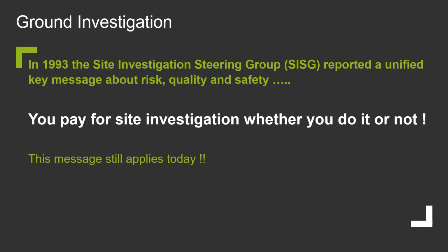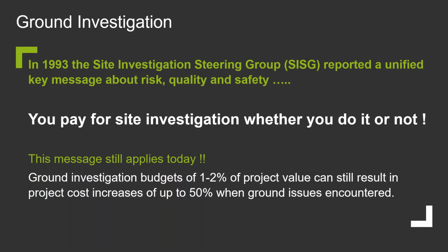So a low-cost site investigation may be low cost initially, but longer term you may pay for it, is the message. I guess you might hit lucky and that not be true, but if you hit unlucky, then there could be consequences. Published research suggests that if you spend around about 1 or 2% of the project value on the investigation stage and the planning, then you may still result in project costs escalating to in excess of 50% beyond project value.